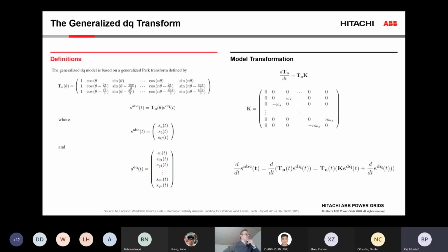Right. Matt, you also mentioned that it all depends on the loading level, these interactions and all operating points. I mean, particularly the things that you detect that are related to PLLs, and the interaction of PLLs and current control is also strongly operating point dependent.